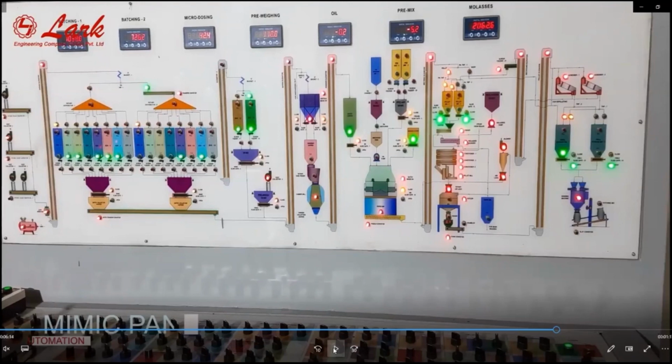And mostly all feed millers run a single recipe at night, because at night there is less awareness and less responsible staff in the feed mills, so to avoid the chances of cross contamination, generally they run a single recipe at night. With a single recipe and less disturbance of loading and unloading, the efficiency should be more. But the opposite, in the night shift, generally feed mills are facing low efficiency with respect to the morning shifts.